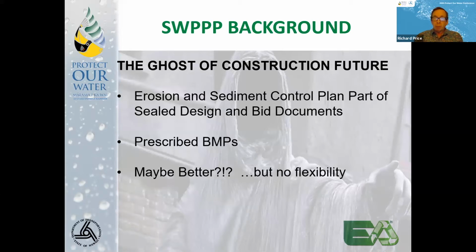And then the ghost of Christmas future, I'll say that in a number of states in the mainland, they now have a requirement that the designer prepares an erosion and sediment control plan, and it's part of the sealed construction documents and part of the bid package. And the contractor's means and methods don't really come into this. They're pretty much prescribing to you what BMPs you're going to use, how you're going to use them.